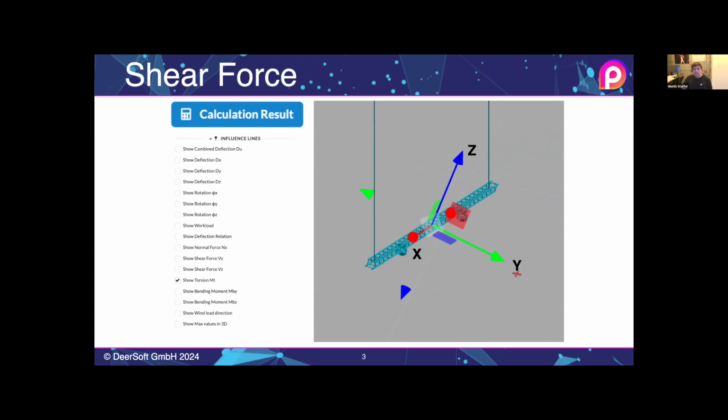Another thing that you see in this example is that the z-axis and the x-axis can actually be tilted in relation to the global coordinate system. So this basically means the z-axis is not always pointing up, but is always locally defined by each truss piece. All of these values that we are seeing, you always find in the calculation results object.